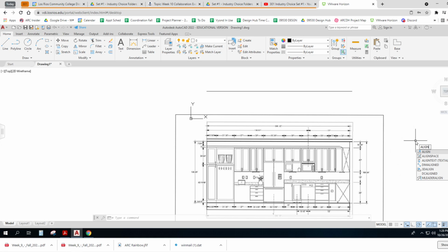Sometimes I get this in earlier and sometimes not. So I can align one part of my drawing with something else in my drawing. If things aren't lined up properly, or they're the wrong size, or at an angle, you can use this, ALIGN. I select what I want to do, click, enter.